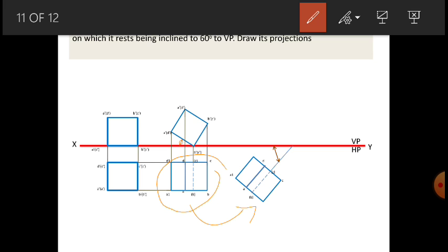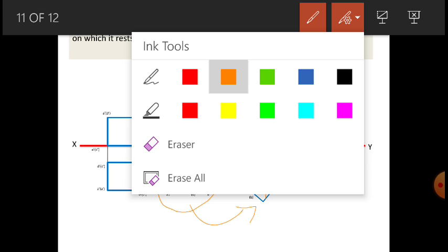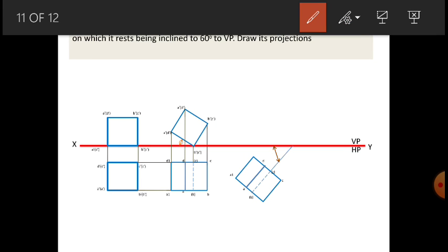Understanding? The same drawing with the same measurements, you are going to tilt it to the 60 degrees angle and project all the corners, going to project it like this above. From this object, you can see you have to project it from all the edges and the intersection points of the object.